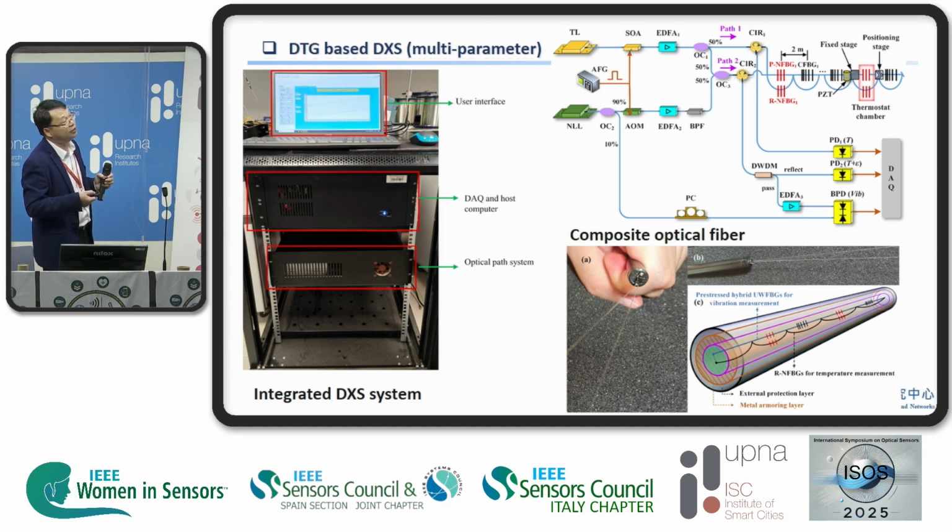That means wavelength measurement for temperature and strain, and phase shift measurement for the so-called acoustic sensing. So that means it's possible to measure distributed temperature sensing, distributed acoustic sensing, and distributed strain sensing in one system, especially in one cable. This is challenging for such kind of technology. We call it distributed acoustic sensing.